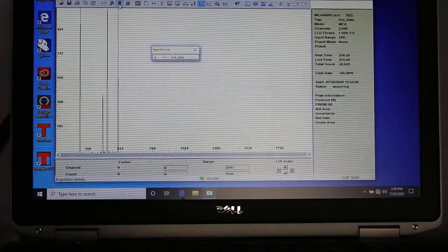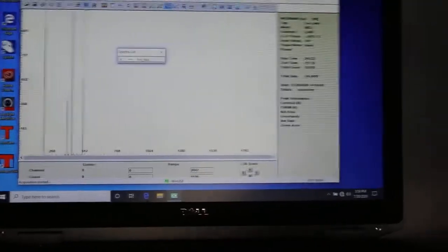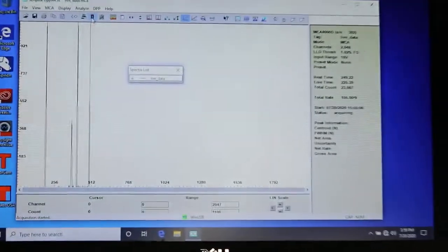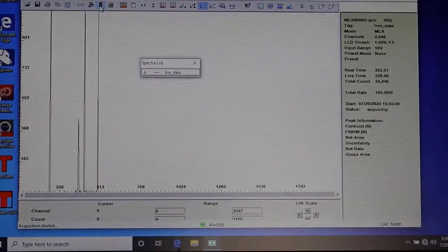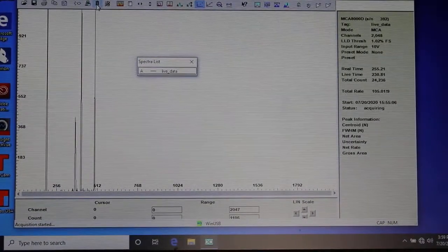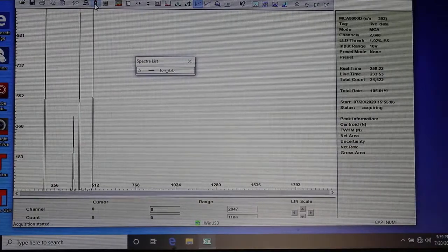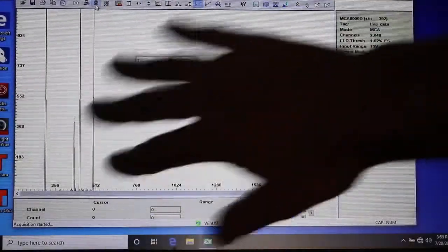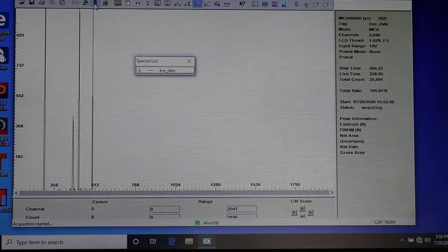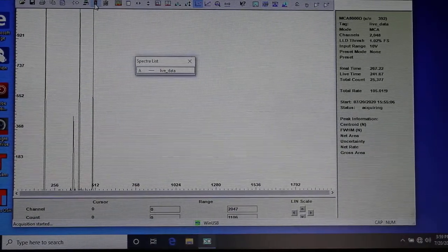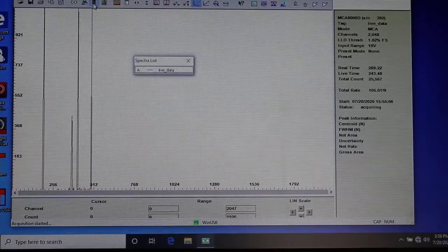So that's what it does, and I hope this experiment with the voltage, using the wave generator on the oscilloscope, has helped you see that. I changed the voltage of this pulse, and I'm seeing how that voltage gets mapped into what channel on the multi-channel analyzer. And so you're left wondering what this voltage spectrum channel map would look like if it was something like a cesium-137 source coming in. We'll leave it at that and pick this up in the next video by looking at some actual radioactive sources.